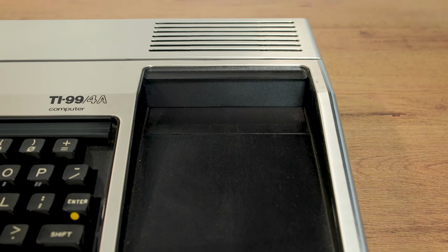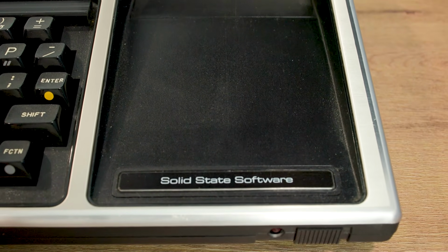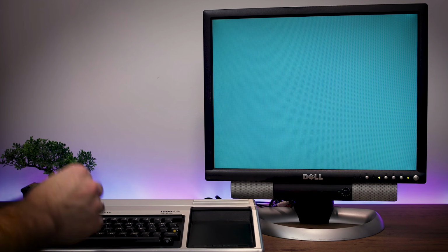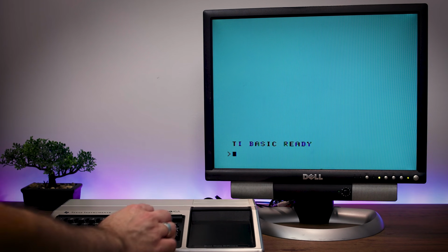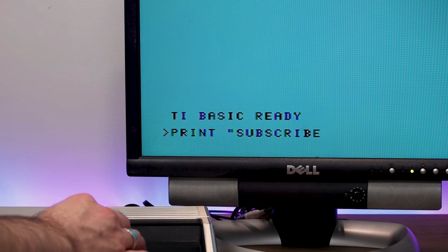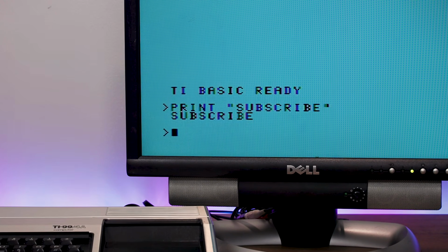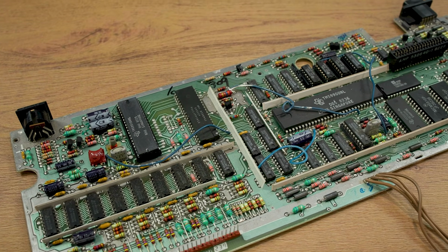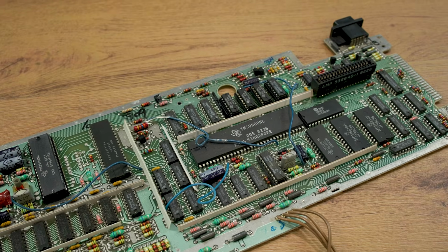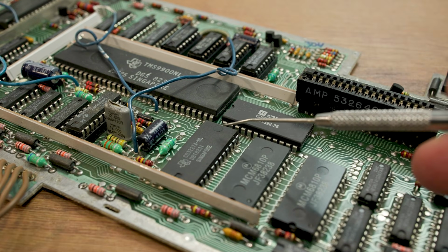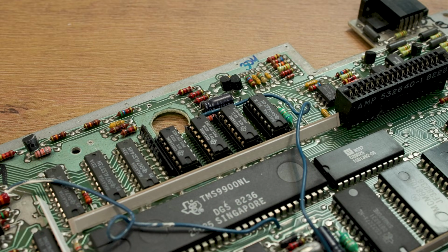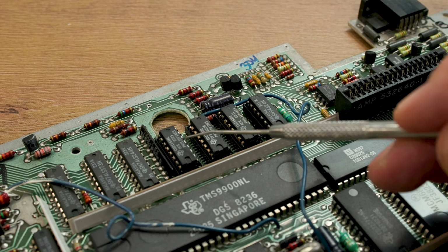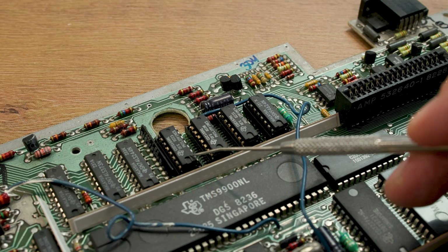But if it's a cartridge-based computer, like a TI-99, it has its own ROM chip built in. So when you turn these systems on without a cartridge, they start executing the program on their internal ROM, which is often a basic programming environment. Now, the TI-99 was odd in many ways. I won't go into the details here, but its internal bus architecture is a little wonky. So TI Basic is technically not built into the system ROM. Rather, it's in something called the GROM.